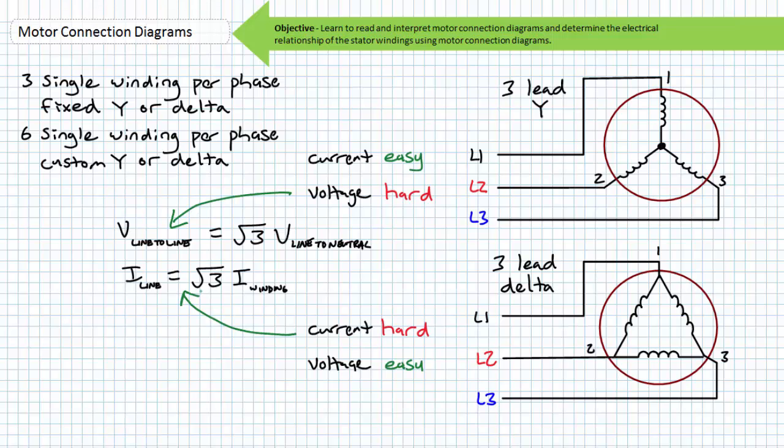For balanced three-phase AC electrical loads like motors, line current will be square root 3, or 1.73 times as great as current through a delta-configured winding. This mathematical trickery allows a technician to take easily accessible line-to-line voltage and line current readings external to the motor, regardless if it is Y or delta configured, thereby circumventing invasive and problematic inspection.